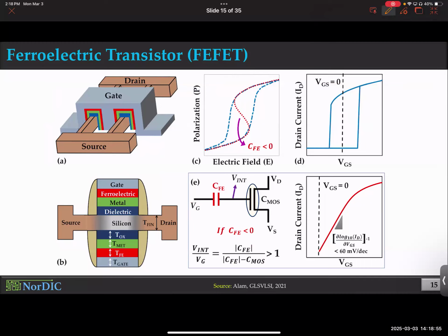So why am I telling you the concept of negative capacitance? Okay, I know this is a very legit question. How is that even related to memory? Apparently, this phenomenon does not only lead to amplification in the internal voltage and make your transistors stronger at lower voltage and thereby make electronics better, it also leads to some interesting design opportunities for memory design. And I will tell you about that. And interestingly, surprise, surprise, it improves SRAM.